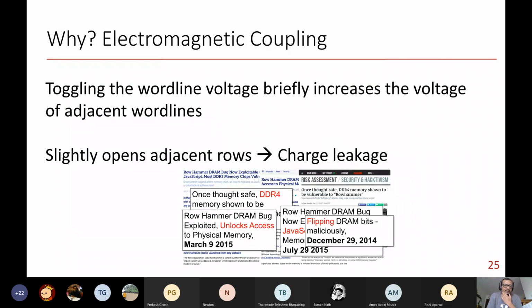One of the reasons for this attack is the electromagnetic coupling. Again, DRAM folks will be able to answer better compared to me, but at a high level, the idea is the DRAM cells are becoming smaller and smaller. Which means, now if you try to access a particular word line again and again, so word lines are nothing but, if you remember your digital logic course, the notion of word line and bit line, right? Which actually stores your final 1-bit information, right? Where you connect a bit line and word line and you get a 1-bit, right?